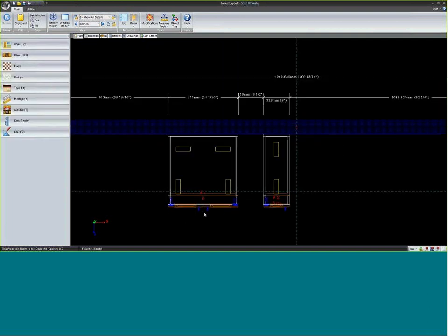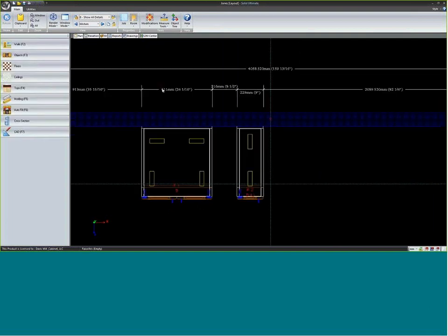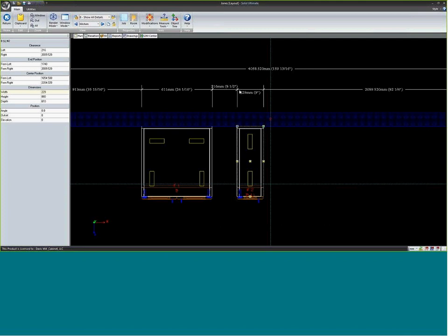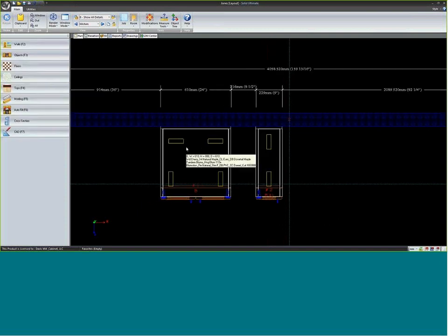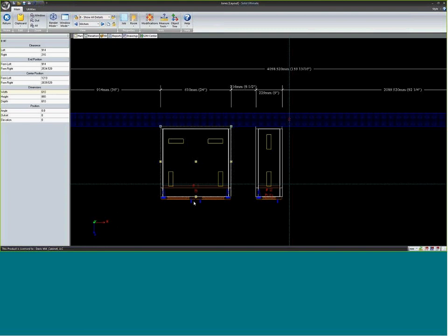So the point is that we want to stick to whole numbers, no fractional millimeters if possible. But in single door applications, any whole number is fine. In double door applications, we want to stick to even numbers, not just whole numbers, but even numbered millimeter increments, if at all possible. That's not always possible. This is one of those rules that can be bent or broken. But it is important to recognize that if you order this at 611, we're going to have to do some door rounding, and in order to do that, you may or may not get the exact reveals you want.